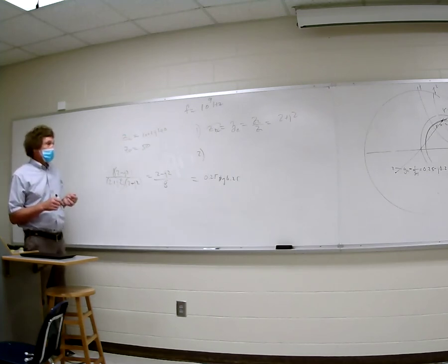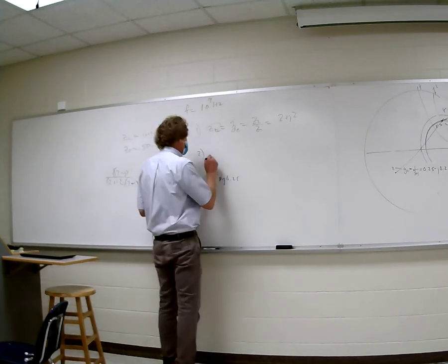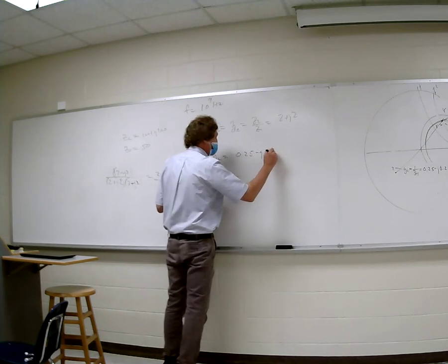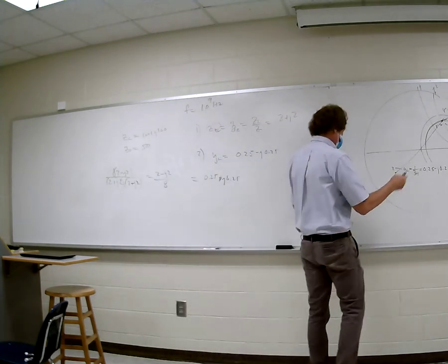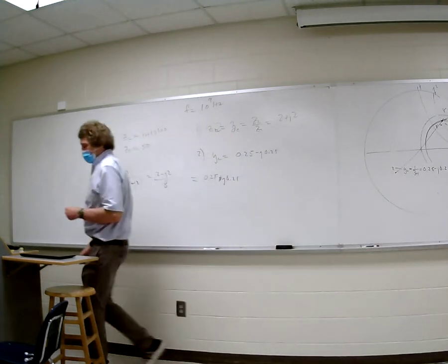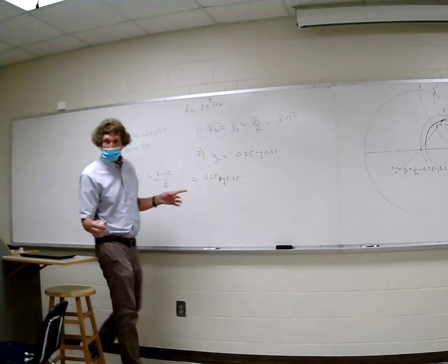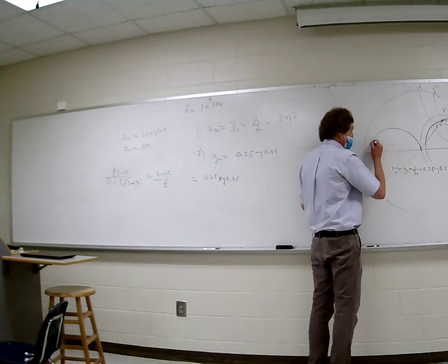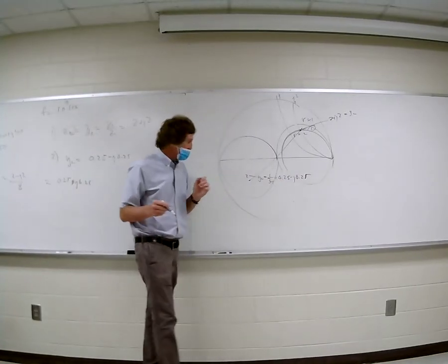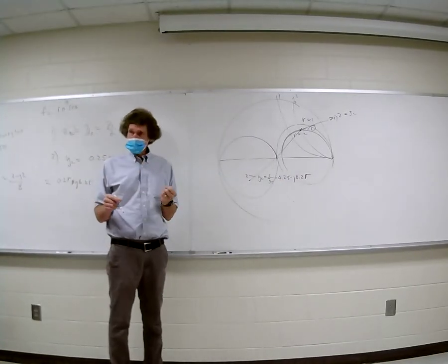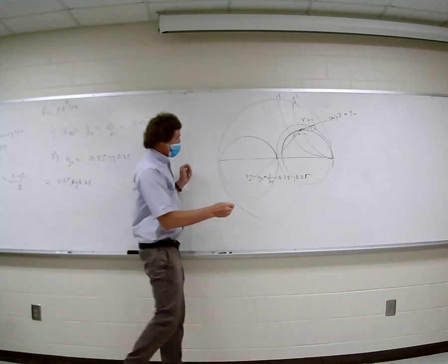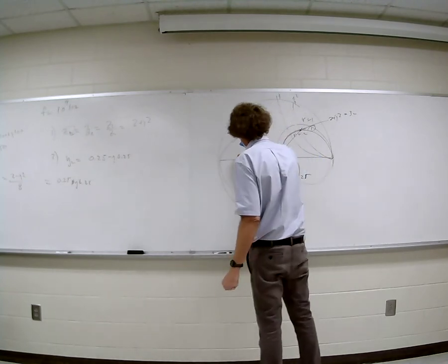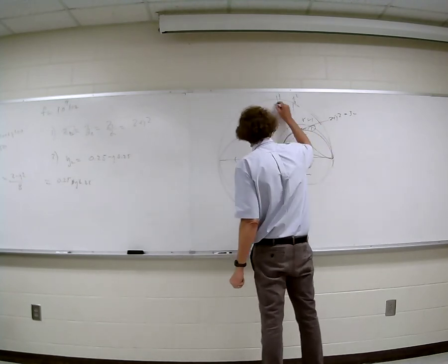So, now we have that. We get YL equals 0.25 minus J 0.25. And this is the question we ask. Now I'm going to have to draw the rotated circle. Now we're in the admittance domain. You agree? We came in impedance, now we're in admittance, we're adding in parallel. Now we've got to see what kind of normalized admittance we want to add. So if I go here, right, there's 2 ways I can go. Just listen to me. Remember that that's the one, this is 0.25. So if you looked at the 0.25 large circle, it would be something like this, right?